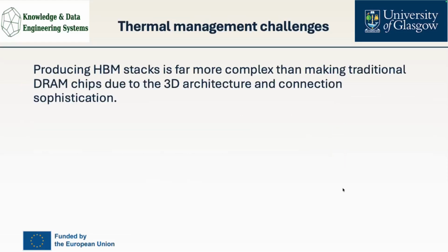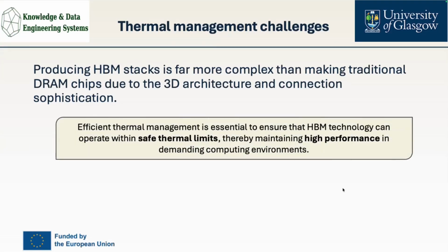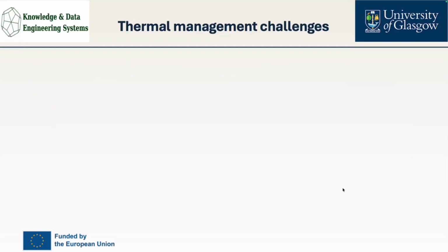So when we talk about the high bandwidth memory stack, it's considered more complicated than the traditional DRAM chips, because we deal with a 3D architecture and the connection is sophisticated. So in general, it's important to have thermal management to ensure high bandwidth memory technology can operate within the safe thermal limit and thereby maintain high performance in demanding computing environments.